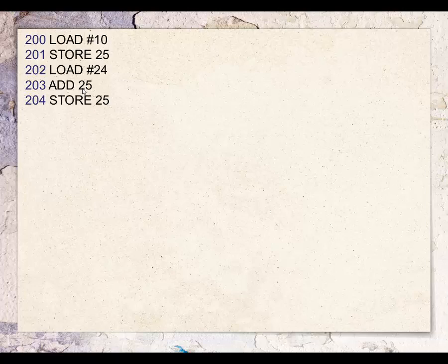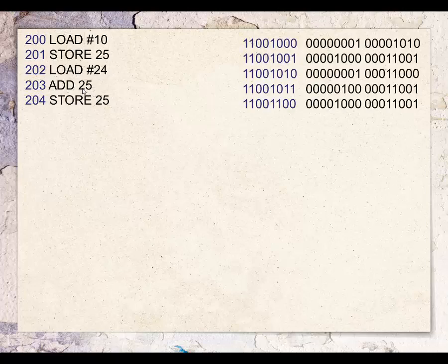What I've now done there is I've given you the mnemonic but with the memory address. I've simply chosen an area of memory. It doesn't have to be those values, but I've selected them. So in memory location 200 will be this data instruction. In memory location 201 will be this memory instruction, and so on. It actually looks like that in the binary. This is the address part, and this is the data part. When the address bus is working, it will work with this, and when the data bus is being used, it's this that will be traveling down it.